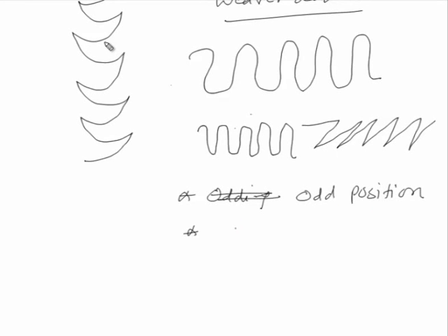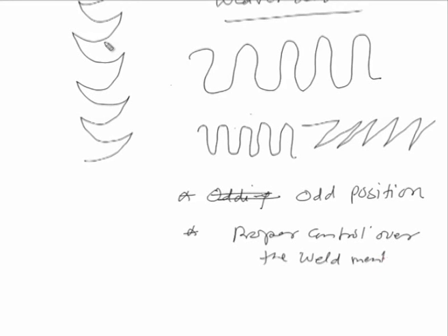to have proper control over the weld metal. Sometimes it is found difficult to control the weld metal properly. So, to control the weld metal properly without any falling tendency, different movements are given to the arc, so that the molten metal gets enough time to solidify and produce the weld metal and the weld joint as desired.